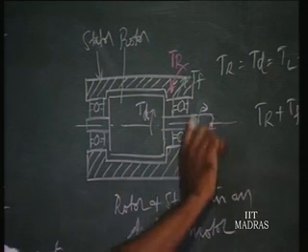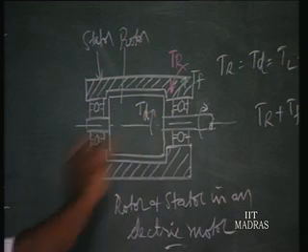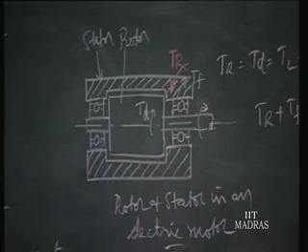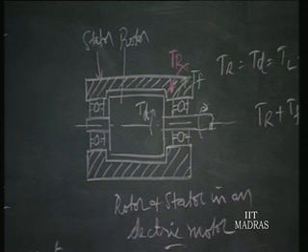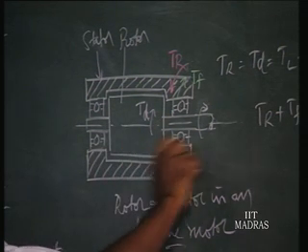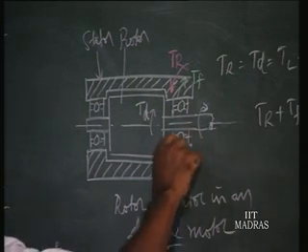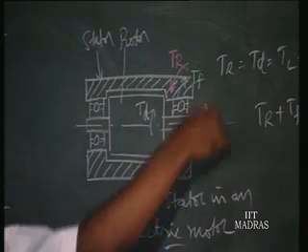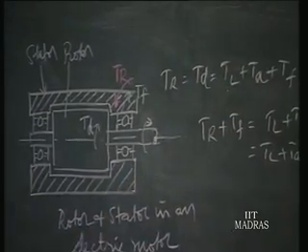Suppose TD is in this rotation direction. So TD is the torque developed in the rotor. Then we know as a reaction, the reaction torque TR is developed in the stator in the opposite direction. Now what is developed torque? Developed torque is made up of load torque acting, and also acceleration of the whole mass; the load mass also should be accelerated. So load torque plus acceleration torque plus friction.